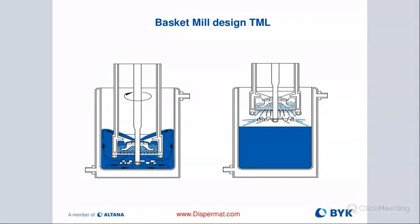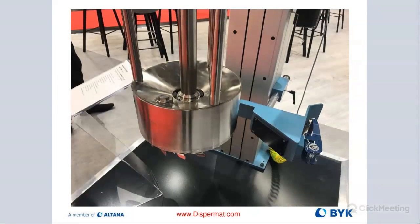Again, sucking it out of the basket. The screen here keeps the media in place, and then we bring it to the top where we rotate it in and out of the basket. That's the benefit of a basket mill. Very good, efficient milling. This is a larger production size basket mill. Our bead loading is right here where that screw sits. We remove the screw, take a funnel, and feed the beads right into that gap. And that's the production size basket mill.